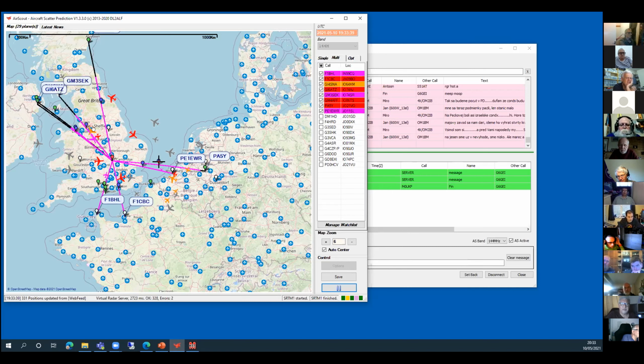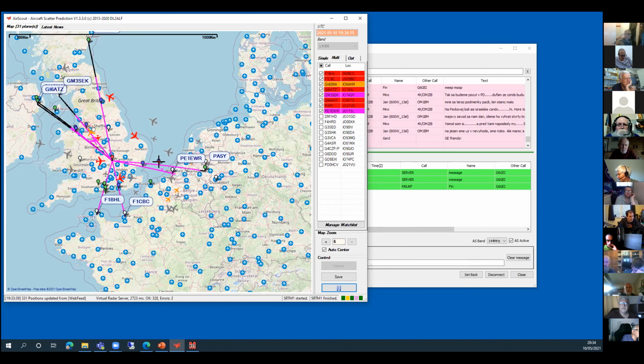Because I missed a little bit of the talk, Tim. Did you say whether it was more effective on 6 and 4 meters rather than 2 meters, or is it equally effective on all bands? It's not equally effective, but I couldn't tell you exactly what the maths is between that. Because one of the other things on the higher bands is more Doppler shift as well, depending on which path the aircraft's in. But it's reliably, you know, the predictability of the software is very good, both on 6 meters right through to 23 centimetres.